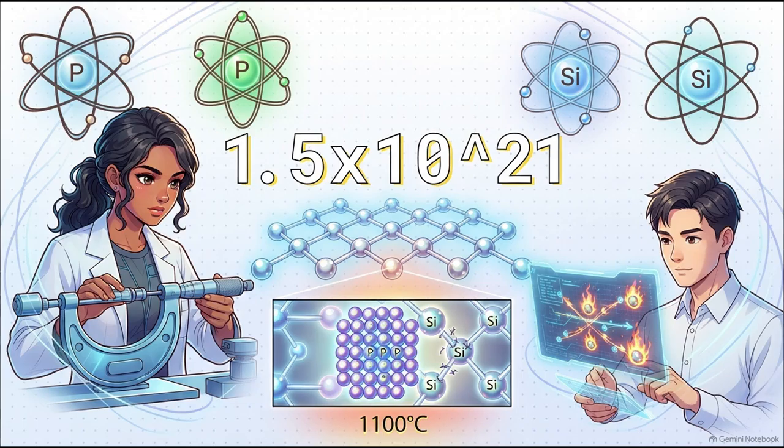Now, to really grasp the sheer mind-boggling scale of this precision, look at this number, 1.5 times 10 to the 21st power. That's a lot of zeros. That number is the actual solubility limit of phosphorus atoms per cubic centimeter in silicon at 1100 degrees Celsius. It represents the absolute maximum amount of dopant allowed before crystal defects start to happen. If engineers push past this limit, the excess dopants actually hinder the mobility of the electrons and degrade the device's performance. It's an incredibly delicate atomic balancing act.